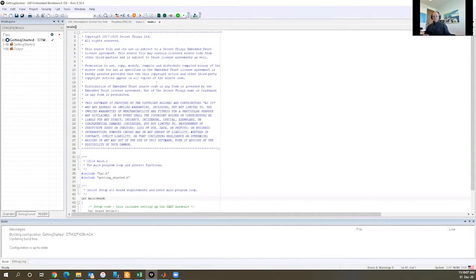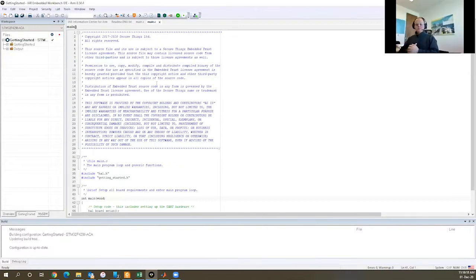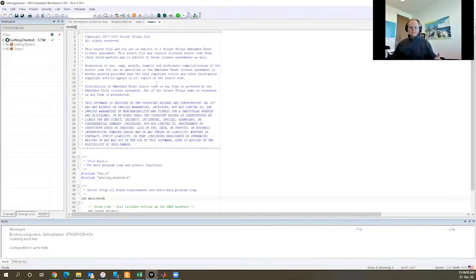Okay. So where we left off is we had created an application, and then we created a secure boot manager and enabled security on that application. And then we were downloading and doing our regular development activities. We had provisioned the board. It had a secure boot manager. We were now working in a secure workflow when the developer does a download and debug, the firmware image is automatically encrypted, and then it gets bootloaded by the SBM. So we saw how all that works in a development organization.